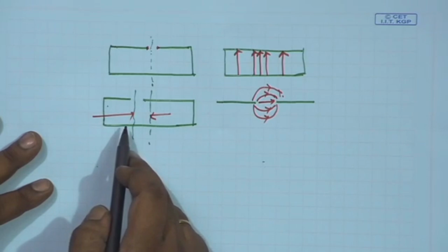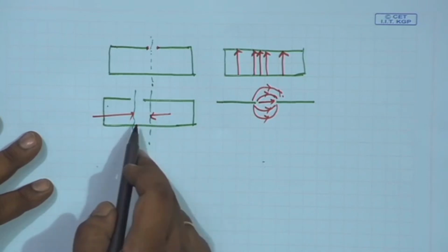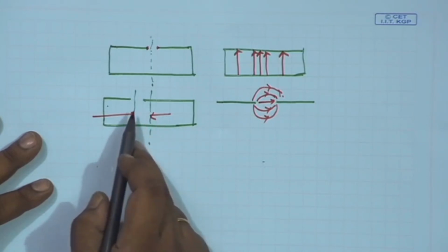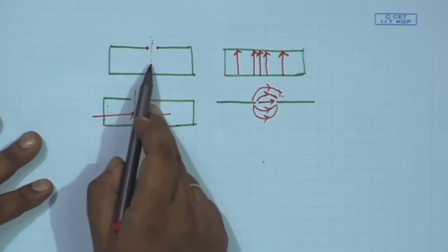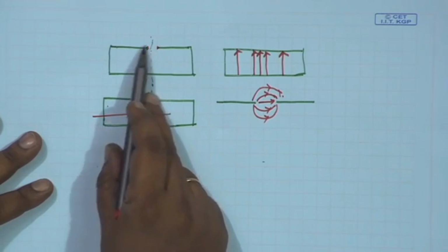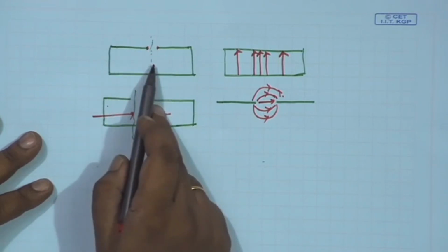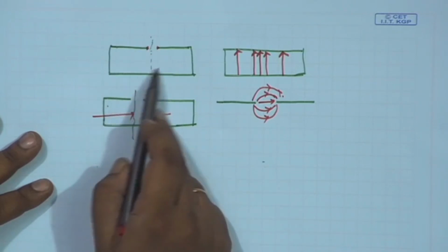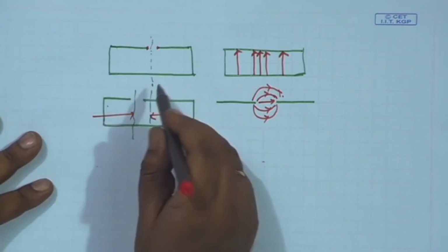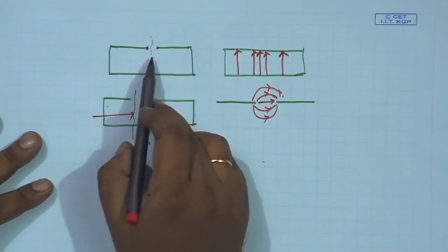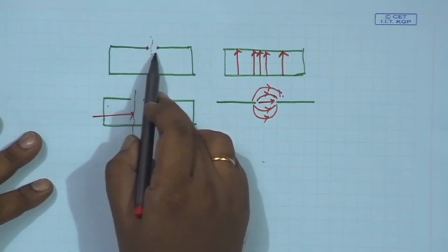Finally, we have to feed the power to the rectangular waveguide over which we are etching the slots. Now, when we place the slot on the central axis, there is no effect on the rectangular waveguide mode, or in other words, for the feeding port to the rectangular waveguide, there is no change due to the slot.